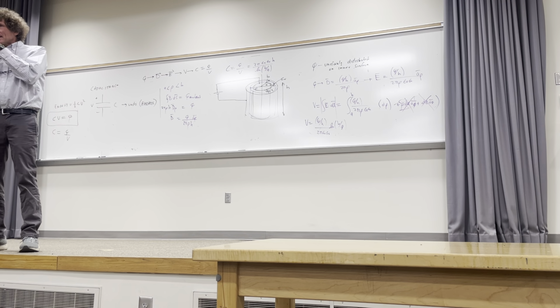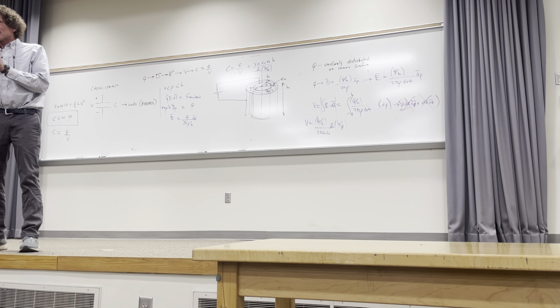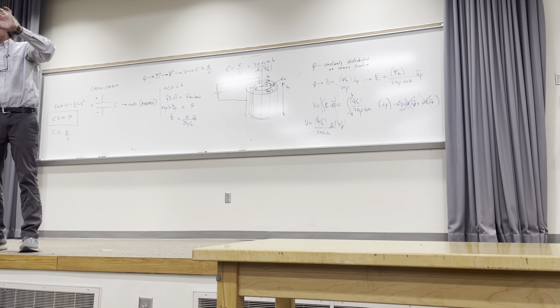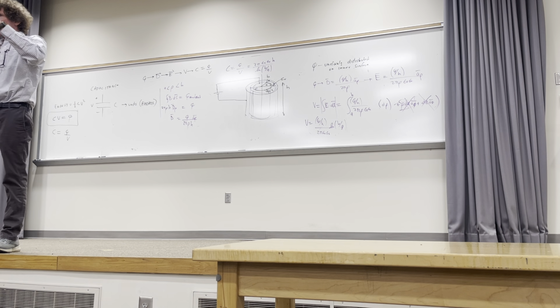And I remember also seeing something about the dangers of, do y'all know what electrolytic capacitors are? I don't know if everyone taught this to you. There's certain capacitors you can only charge a certain way. If you try true AC current, they'll blow up because the dielectrics will start flipping. Instead of the molecules being in the same direction all the time, they'll try to rotate and generate a tremendous amount of thermal heat and they blow up.